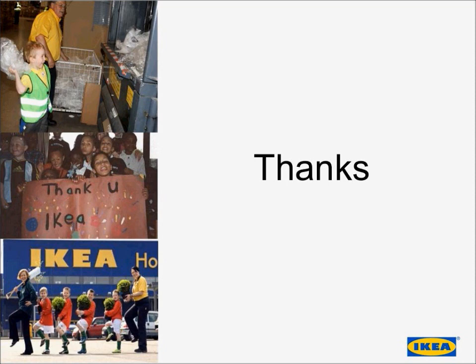It's a good question, and has got quite a lot of information in it. I'll do my best. Energy from waste is a really vital part of the zero waste journey. I think the concern, as I said in the presentation, is that different materials, when they go through a mechanical sorting process, handle in different ways. So, for example, if you have mixed materials going through a recycling facility, then potentially paper grades may react in a similar way to plastic films. When paper grades are wet, then they may get stuck to other materials, and so there's a potential that we could lose valuable cardboard, paper, plastic grades through pushing too much material too quickly through mechanical sorting processes.